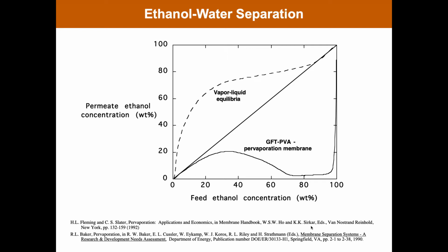Last little tidbit. The alcohol that goes into the rail cars is typically better than 99% ethanol. It's way past the azeotrope. What's required by fuel grade standards, by ASTM, is on the order of 95, 96%. Why would you purify it to above the requirements for fuel grade alcohol? Start taking water from the air.